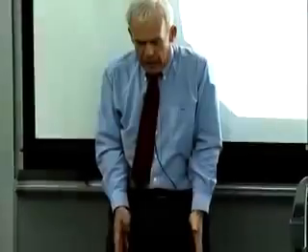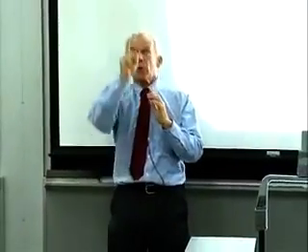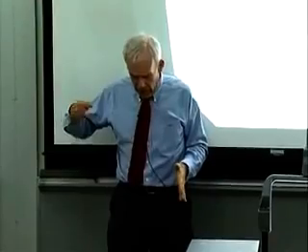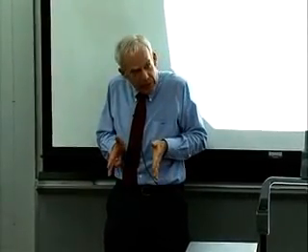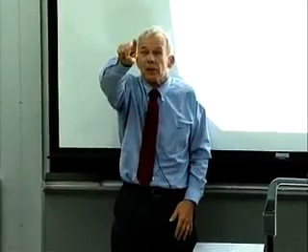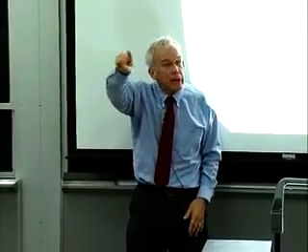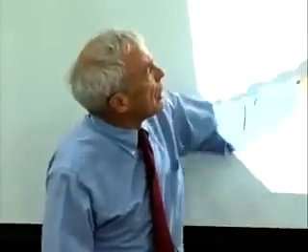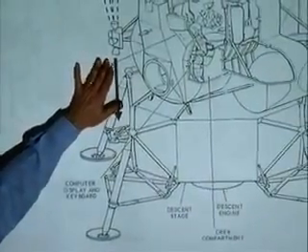In case you didn't luck out and have that thrust go right through the center of mass, you were going to have a biased torque, and then these little jets were going to have to pulse to keep things on track. So this descent engine had a capability with a worm gear that could gimbal it very slowly, 0.2 of a degree per second. So sort of like 2 seconds to go the width of the moon, you know. The moon's half a degree across. So 2 seconds to go across the moon one way, 2 seconds across the other. Very slow gimbal capability, just meant to trim out the bias torque so that these little 100-pound, 400-Newton thrusters could do the job of attitude control with their occasional pulsing.